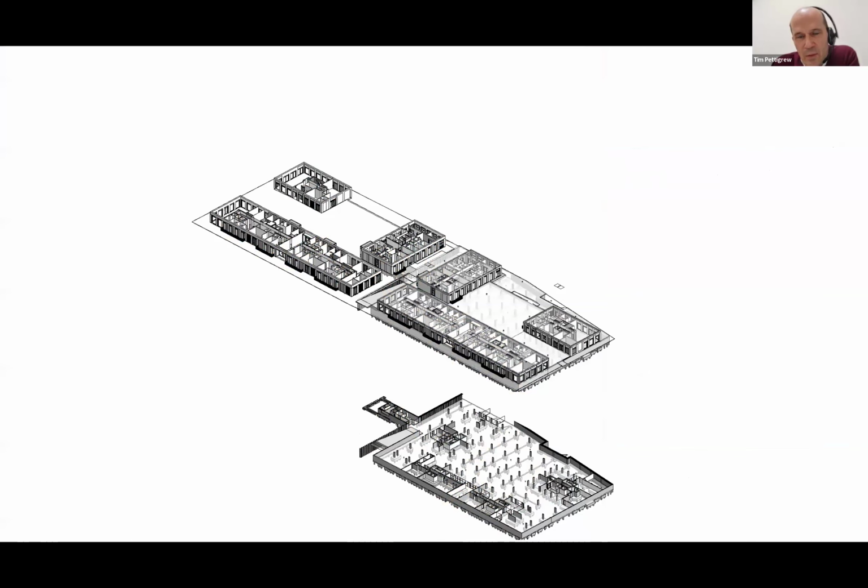What we've done with this is, building panelized facades is obviously most efficient when you've got standardized elements. When you're looking at the ground floor, that's obviously not so standard. You've got changes in floor levels, you've got impact of different facades, different entrance sequences and everything. So what we've done in this scheme is taken the basement level and the ground floor level in traditional construction methods, and then we've jumped from that level, first floor slab, through to the roof in the panelized facade system.